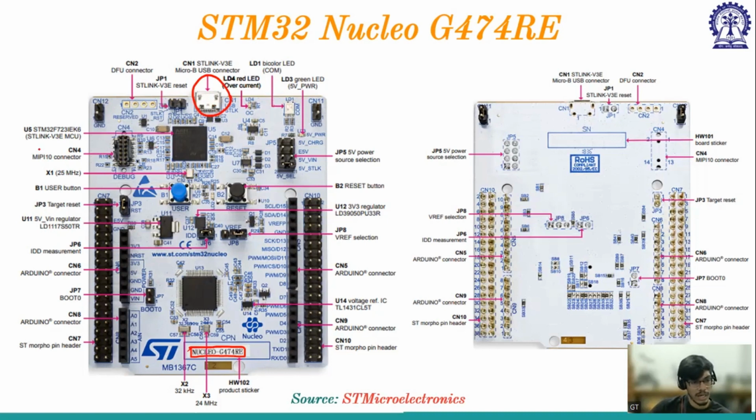And this is the MCU, the debugger ARM Cortex, and this is the microcontroller, which has all the ADCs, comparators, everything inside. And these are the extra pins, GPIO pins, which you can use for any PWM generation or other signal generation, high side signal, low side signal, or if you want to give a load transient, we need to give a pulse. So all these external pins we can use.